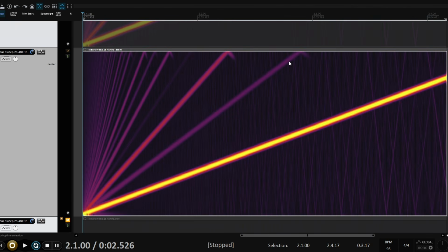Sometimes you'll see little stubs of reflections that fade out before they get back down below 20 kHz, indicating a slightly higher filter cutoff. Which approach is best is largely a matter of opinion. The main thing is that aliasing doesn't get into the audible range, and these examples have achieved that admirably. This is what proper oversampling looks like.